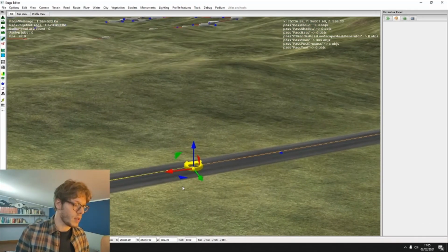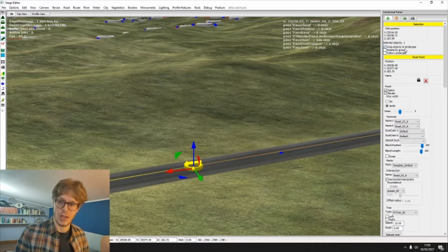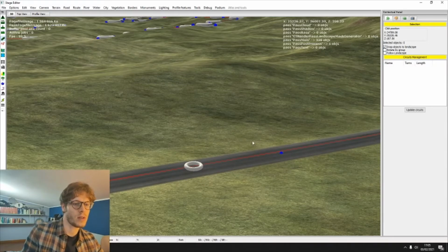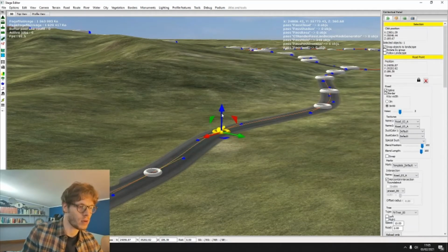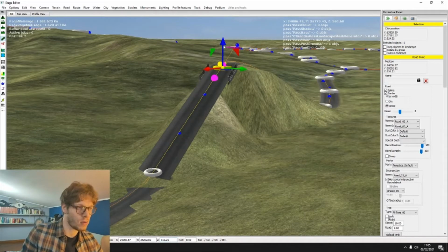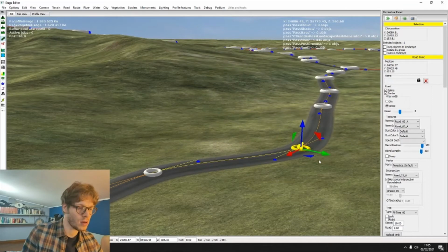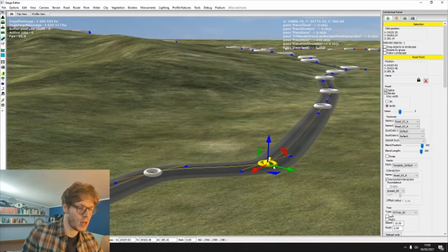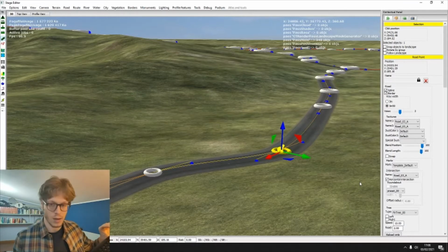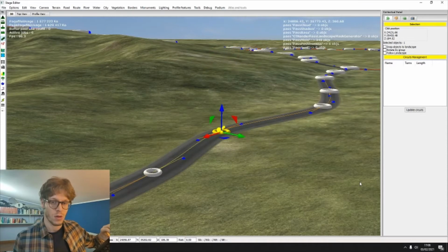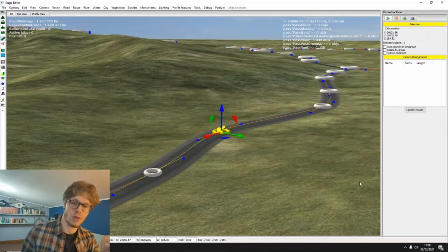What are these points that appear, this direction that appears on the points? Snap. This means that everything we are going to do on this map is going to be snapped to the landscape, to the terrain. If we try to move up or move down, it doesn't work. But if we select this point, we can move up or move down the point. We can move to the right, move to the left, and then with this, move freely, a bit down, up, or like that. If you press Ctrl Z, you go back to what you did before. This is very useful to make good profiles of the stage and to place the objects.